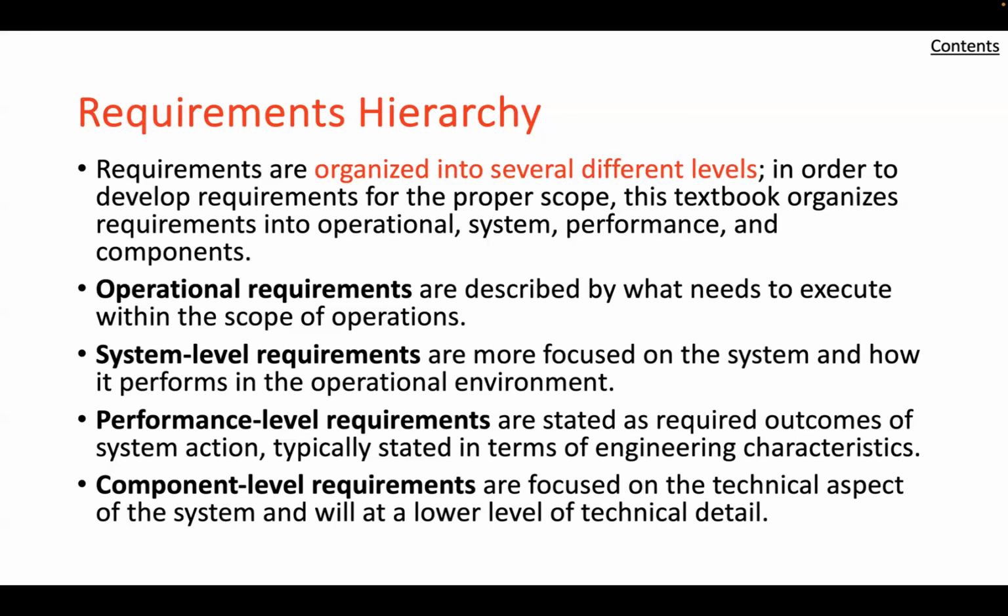So RMA, like we mentioned, reliability, maintainability, and availability requirements, when explicitly stated, tend to be arbitrary and often not well defined. For the other two categories, requirements are often largely confined to the system's operational mode and leave out the conditions of shipping, storage, transit, assembly, and supporting the system. In these circumstances, it is necessary to investigate in detail the entire life of the system from product delivery to the end of its operational life and disposal.